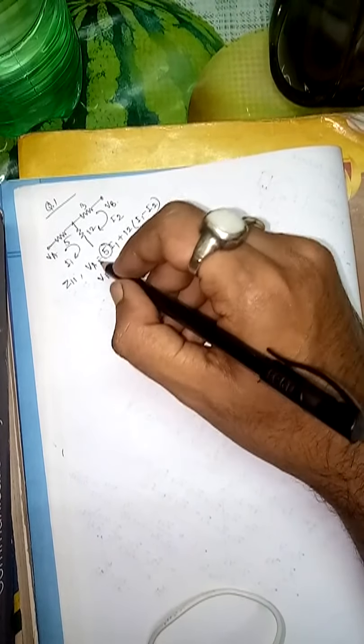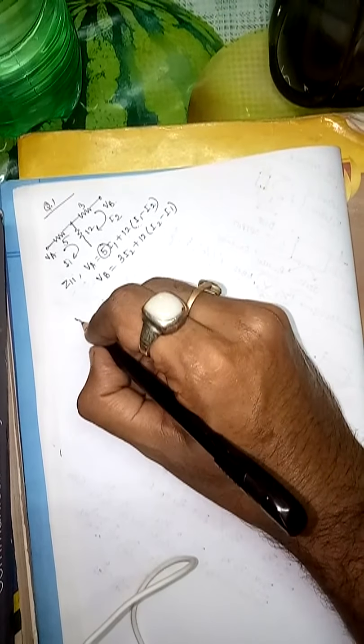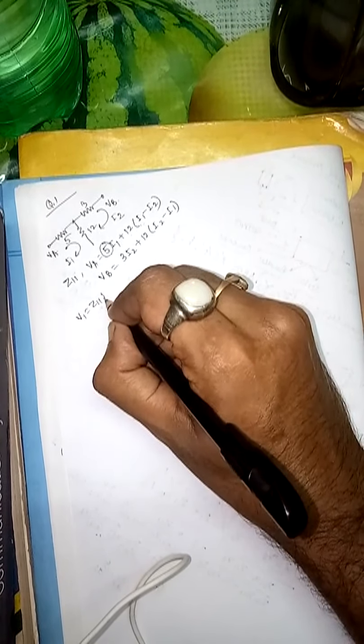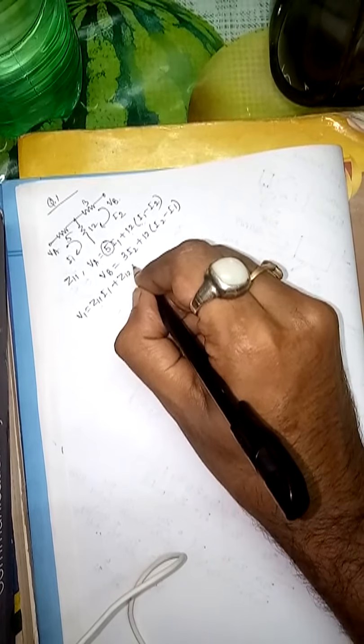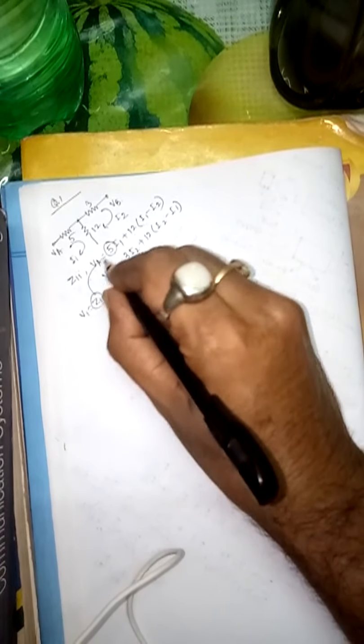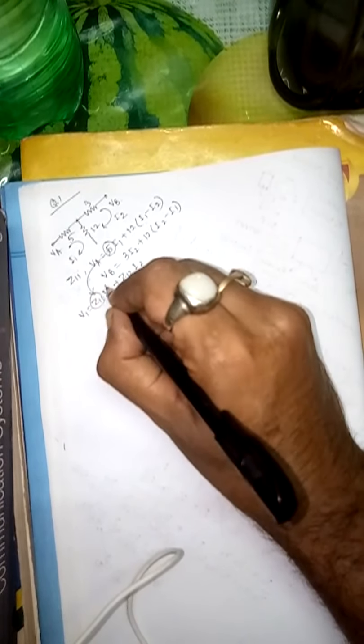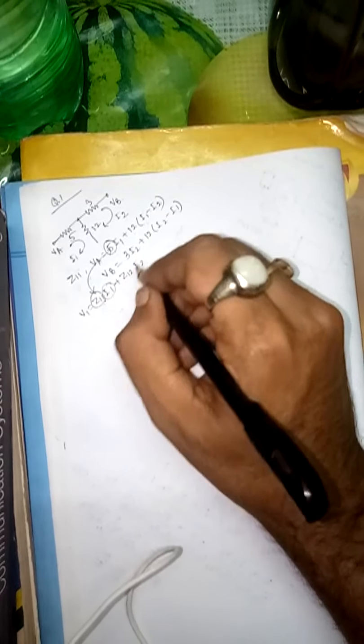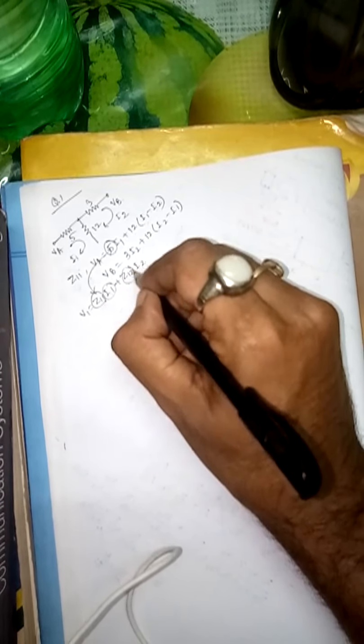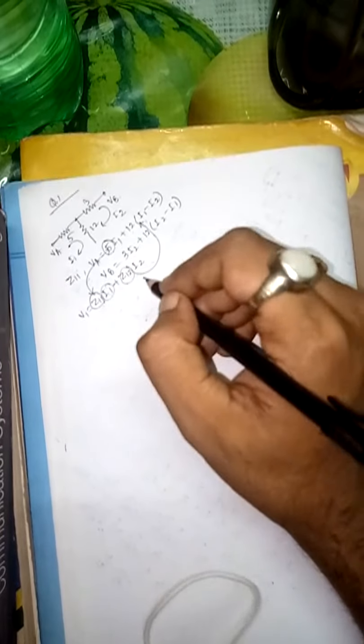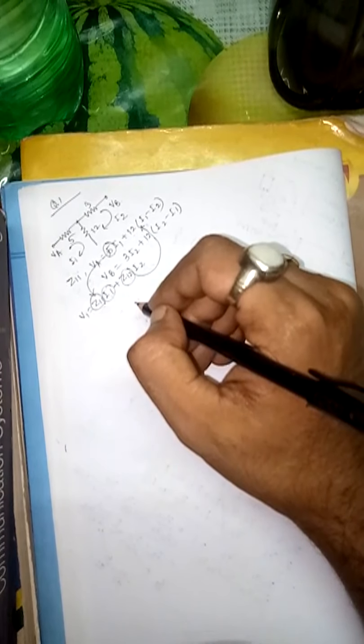So what is the pattern? That is a Z matrix. So V1 equals Z11 I1 plus Z12 I2. So here you can easily find out what is Z by the coefficient of I1. The coefficient of I2, that means minus 12, is basically Z12, like this. So you have to find out the entire mathematical problem in this way.